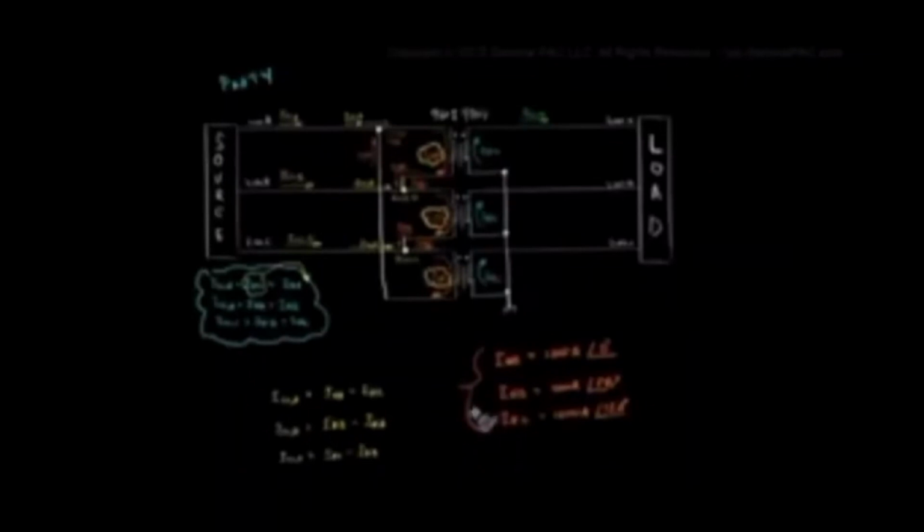We're performing the phasor analysis because we want to relate this line current to this phase current and this phase current, from the nodal analysis on node A1. What we're trying to solve with our phasor diagram is this particular equation: we're going to find out what this line current equals when we subtract phase current C from phase current A. Let's draw the phasor diagram.